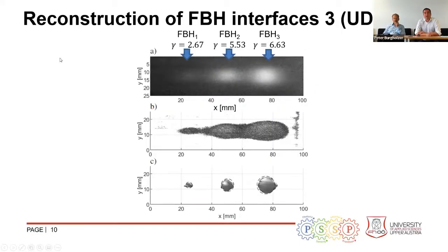A very high benefit you have when you apply this technique to unidirectional samples, because you have a very high thermal conductivity in the direction of the fibers. And you can see here again only the temperature contrast image. You are not able to distinguish between the defects clearly. You cannot see this very deep flat bottom hole.